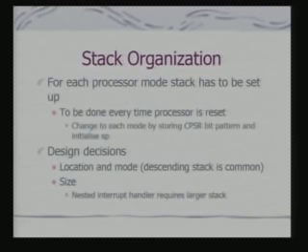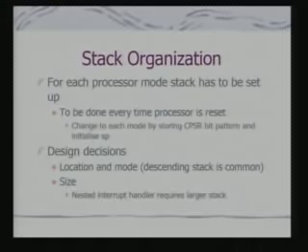If you overrun your vector table by a stack overrun under an error condition, you are corrupting the system as a whole. So, you should associate a location with a stack so that you minimize your chance of overrunning the vector table. And in many cases you can actually use a check to find out whether you are overrunning the stack. And the size varies from implementation to implementation, application to application, depending on how you are designing your software.